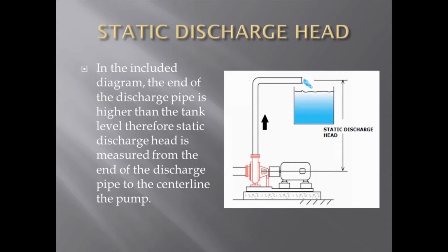In the included diagram, the end of the discharge pipe is higher than the tank level. Therefore, static discharge head is measured from the end of the discharge pipe to the center line of the pump.